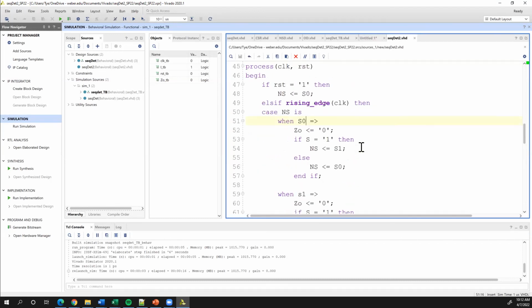And if I'm honest, I would say that I build 90% of the state machines that I build in this style with the outputs combined inside of the states, because it's very easy to think about having states with specific outputs rather than worrying about the timing of a Mealy type machine's outputs. Now, I say 90% because sometimes you really do want the output to update as quickly as it can rather than waiting for the next clock. There are situations where that applies, not as many as Moore state machines in my experience.